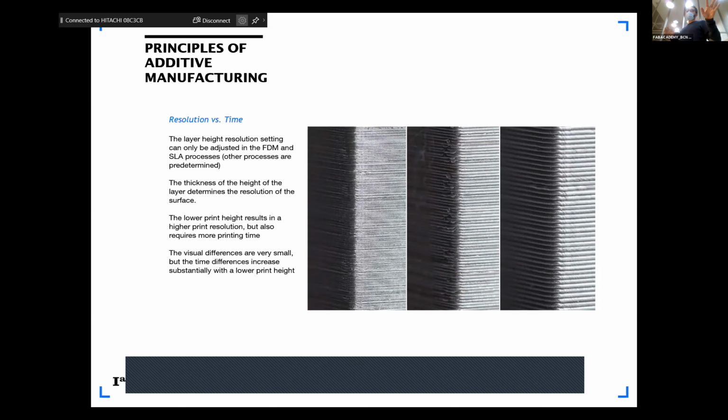In our case, we have some constraints. The material doesn't dry up immediately. The clay that we are using takes at least 24 hours to dry, so you cannot produce super large objects at once, because the material is fluffy and collapses under its own weight. At the scale we're going to work today, that's not a huge deal. But the big towers you see on the door were printed in batches. Half of it was printed one day, and when it was a little bit dry, they printed the second part on top. It continues, but they stop the printing mid-print.